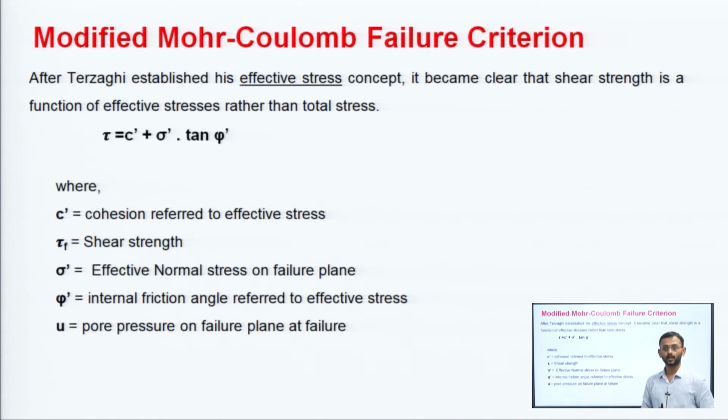Okay, what happens then in 1900 and after 1900, lot of studies were going on in terms of the soil. Now understand that Terzaghi in that point of time, okay, 1900 to 1925 and 1930s, in this point of time he established his effective stress concept, and because effective stress concept was developed, so simply he developed all the other things in terms of effective stresses. So shear strength was given as a function of effective stress rather than the total stress, because the water will also be trying to make some changes.